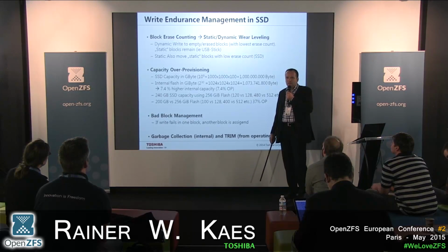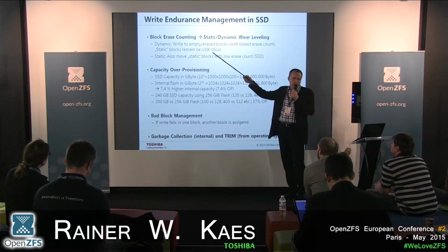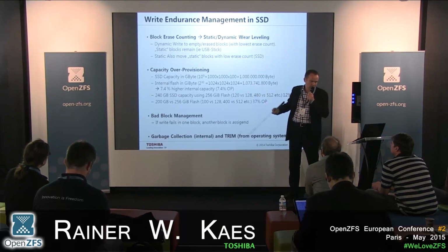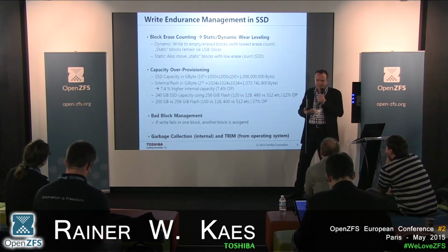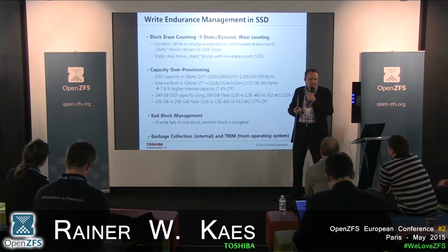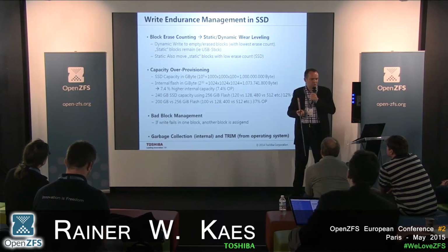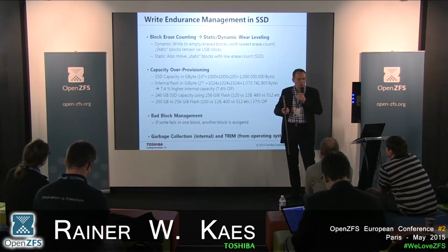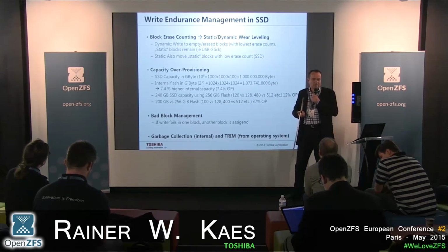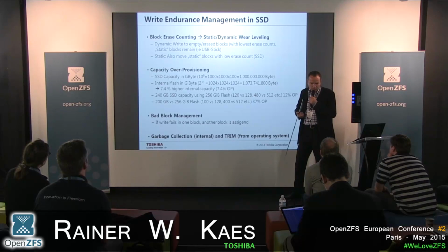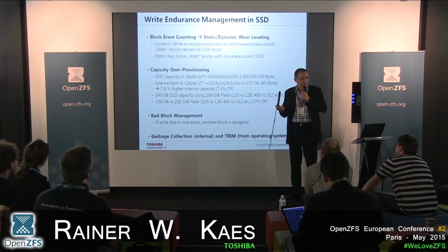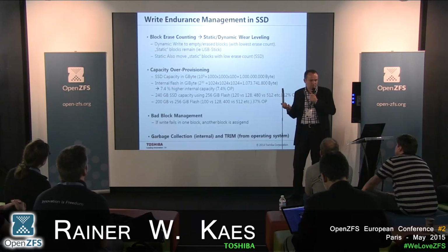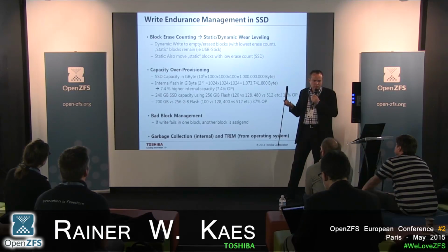For SSDs, the issue of the static blocks remaining may become a problem. So imagine this scenario: you have a 128 gig boot disk with the operating system and application software. If it is a laptop, there are the family pictures and some data sheets that are never changed. And you do your active, hot data, your many erase cycles, on the upper 28 gigabytes. Then the first 100 gigabytes remain at erase counter 0 because they were installed once and just sit there. And you are increasing the erase counter of the upper 28 gigabytes quite fast, and you wouldn't have much fun with your SSD.